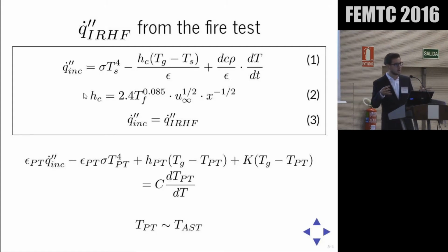In a very simple way, if an exposed body is far away from the fire source, it will be mainly exposed by radiation, and hence the adiabatic surface temperature will be closer to an effective radiation temperature, TR. But if the exposed body is exposed mainly by convection, the adiabatic surface temperature will be closer to the gas temperature. So it will move around as a sort of average.